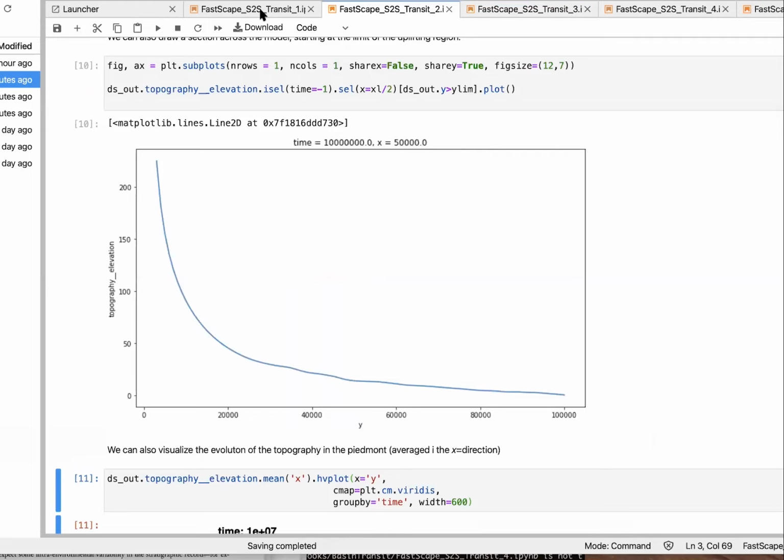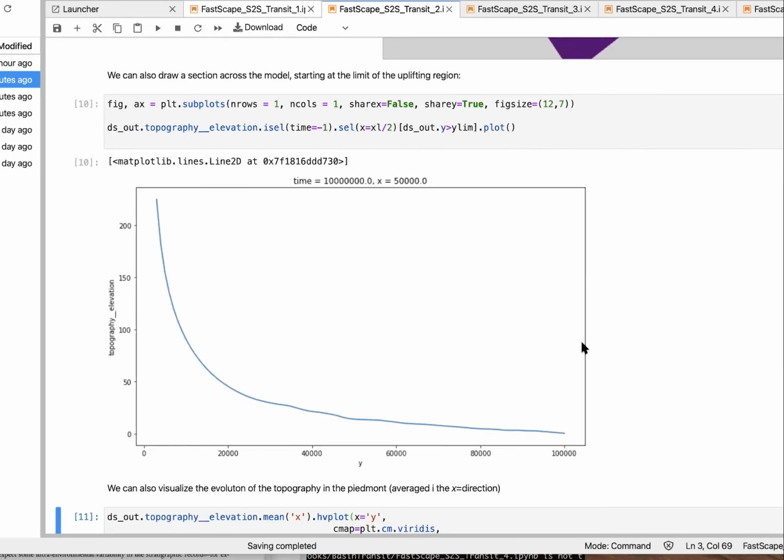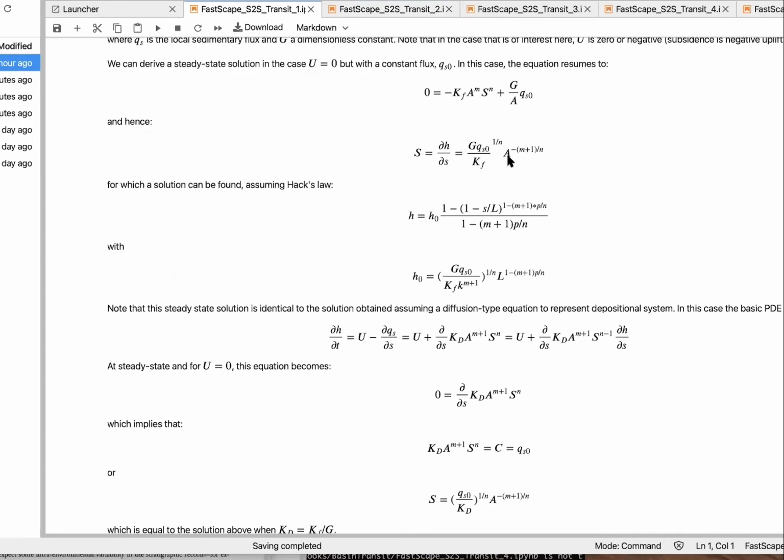This form, okay? And I told you, you get this by taking either the classification that sedimentologists use or the diffusion equation. Both of them lead to the same predictive profile. That assumes, as I said, that to get from here to here, drainage area obeys Hack's slope.